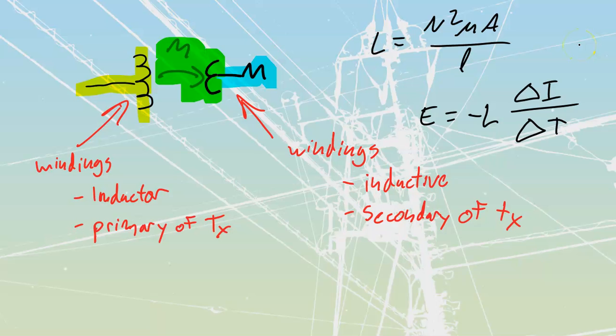We're also going to use formulas that we have seen before, more so in DC, but we're going to apply them inside of AC. We're going to use this one over here, EG is equal to K phi N, and we're going to add on another section to that. We're going to add on a cos theta, which is going to be a power factor, and it's going to tell us about the amount of counter EMF that we are going to have inside of there.